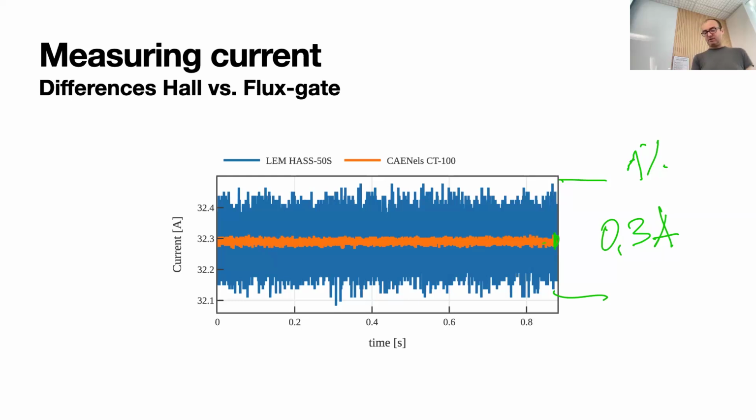And with such a negligible noise level, we can measure current so precisely that in a laboratory setting, this is really, really handy. This sensor has better characteristics than the shunt that I brought here, and the shunt has, I think, 0.5% accuracy. This one is far, far better, but accordingly, the price has sufficiently more zeros than the shunt. And this is one of the design choices.